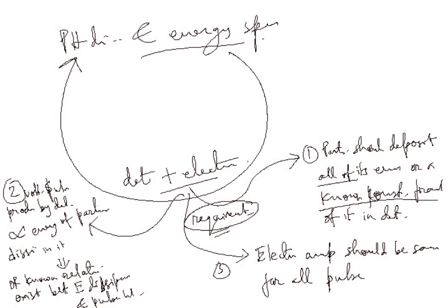Now, you see, the events that transform the particle energy into a voltage pulse are statistical in nature. That also we know. Random behavior. As a result, even if particles deposit the exact same energy in the detector and the amplification is the same for all pulses, the output pulses will not be the same. This is very important, but also a sad thing. But this is reality, nature.